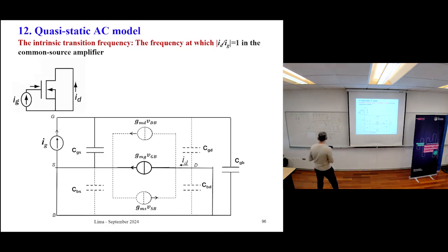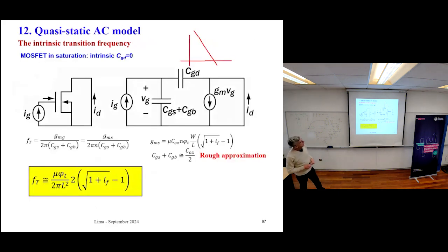So if you analyze this circuit, you have a response such as this one. Okay? Approximate. In fact, we should take into account that CGD, because CGD is in parallel with these two guys. Okay? Not in parallel because it has an effect here. There is this current zone. But for the input impedance, it's in parallel with this.